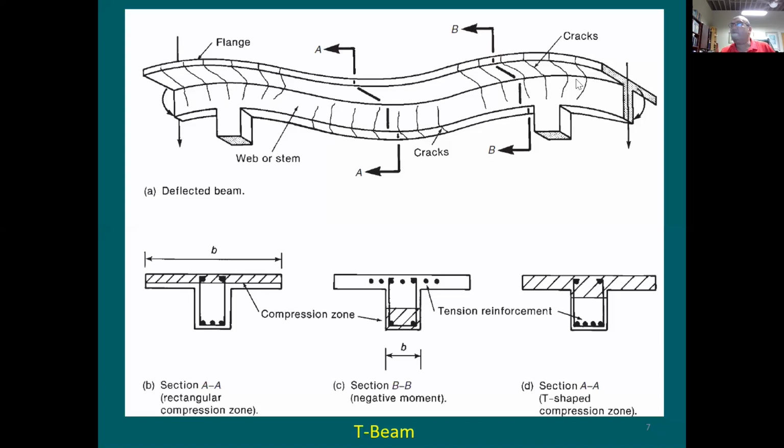If you'd like to add some reinforcing, where should I add it? Reinforcement is mainly needed on the tension side of the beam. So in here, I'd like to add the reinforcing right here to take the tension force. And here, I'd like to add it on the top. This is the main purpose of adding reinforcement. Let me look here at these sections.